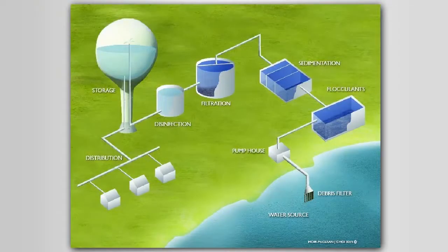Water supply treatment methods used in community systems purify water to an acceptable standard for some specific use, for example, drinking. Most water treatment processes include some form or combination of forms of coagulation, sedimentation, filtration, and disinfection by chlorination.